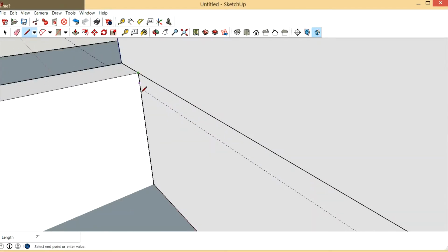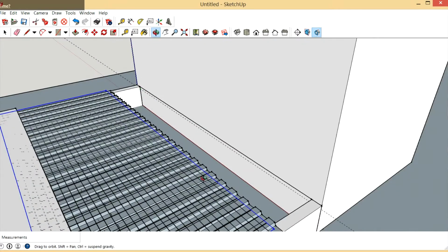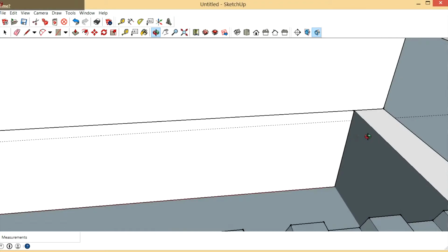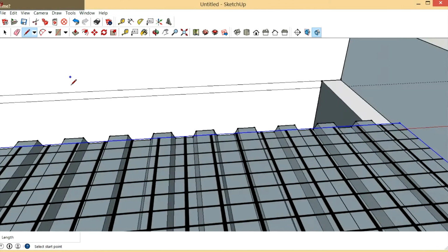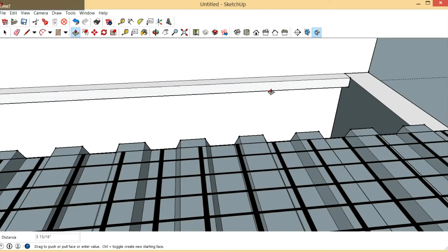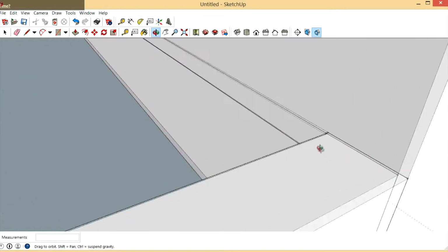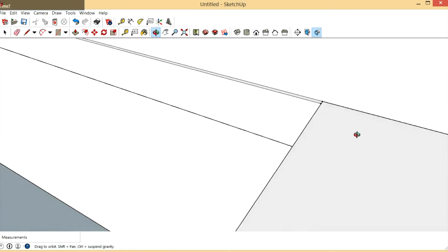And I know this video is kind of long, but the other thing I'm trying to do is show you how this software works at the same time, how SketchUp works. That would be about a 1/4 inch thick, let's just say. So I'm going to pull it out here and I'm just going to type in 1/4. Okay. Now if you zoom in, you can see it there.